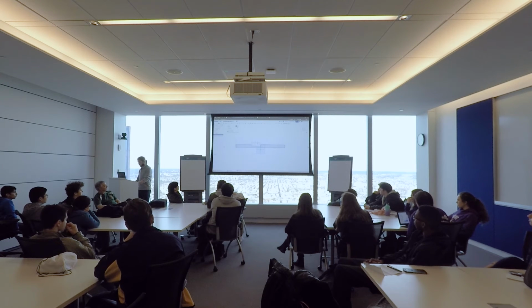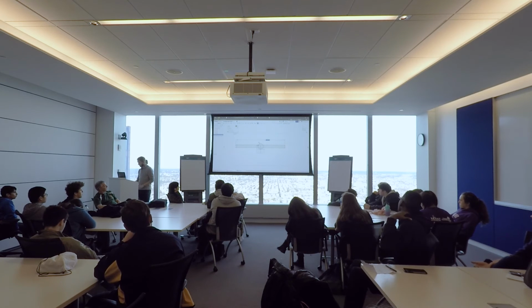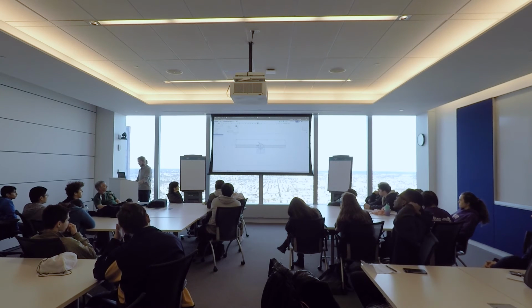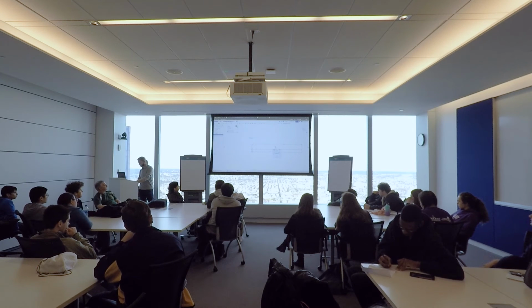We're just going to draw one wheel in the center just so that we have something to define a height. Or we'll make that tangent to the top plane. And then this is going to be 3/6. Sure. I'm going to make this all construction geometry for now, so it doesn't bother us too much. So let's say you have a roller on an arm.